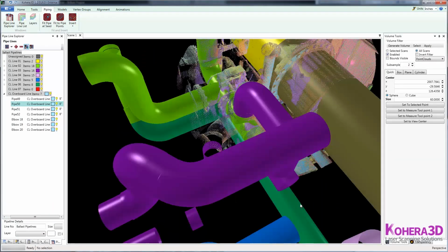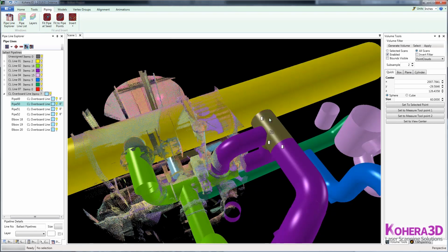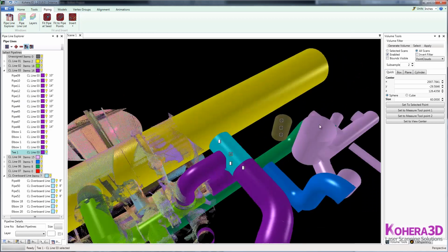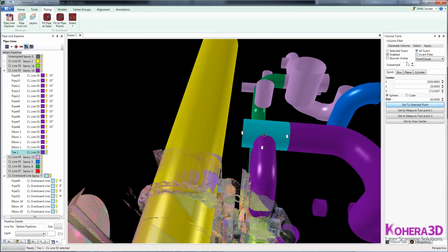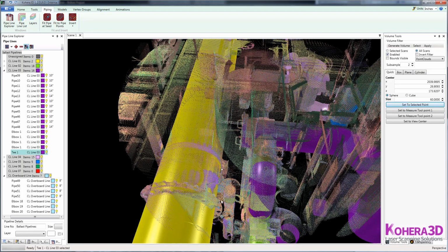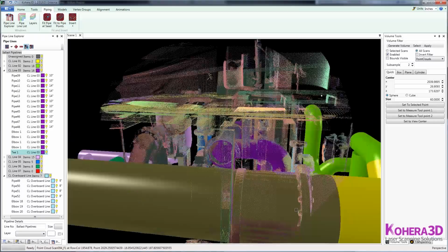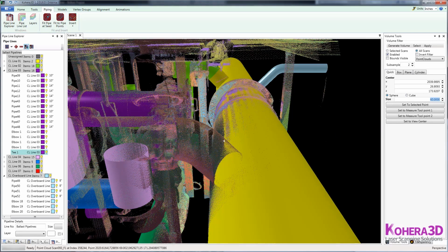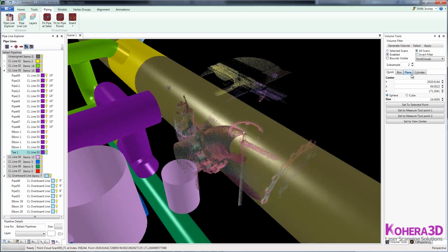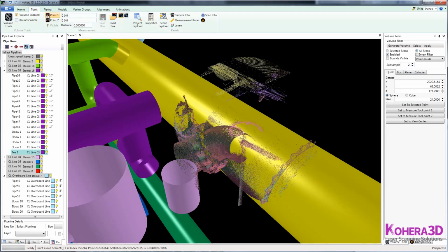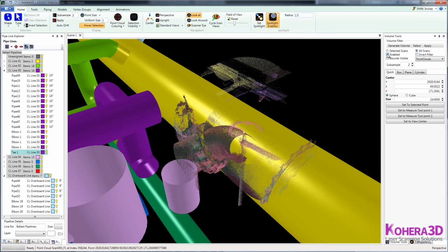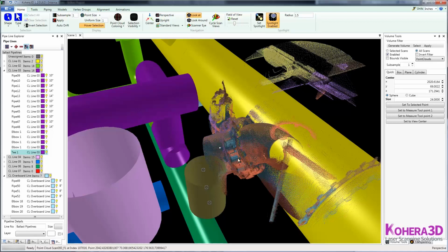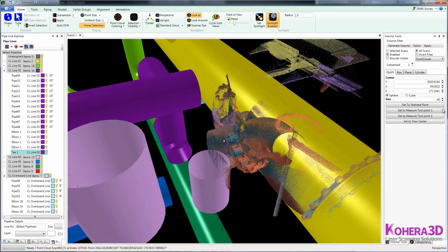All right, so let's look at a couple other areas here maybe. Let's take a look at this. I'm going to set to selected point, click apply. All right, here, let's do this one right here. I'm going to reduce this number. We'll go back down to 24. And again, if we need to see more detail, we can use the spotlight. Or we can even set the subsample to 1. All right, so I need a little more data in this area, so I'm going to bump that up to 40.